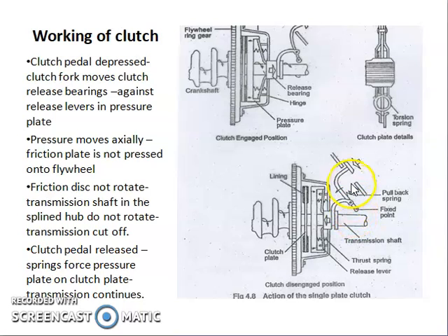Once the clutch pedal is released, the compression springs again force the pressure plate onto the friction plate, forcing the friction plate to attach itself to the flywheel. And then the clutch comes to the engaged position and the power is transmitted. So this is the working of a single plate clutch.